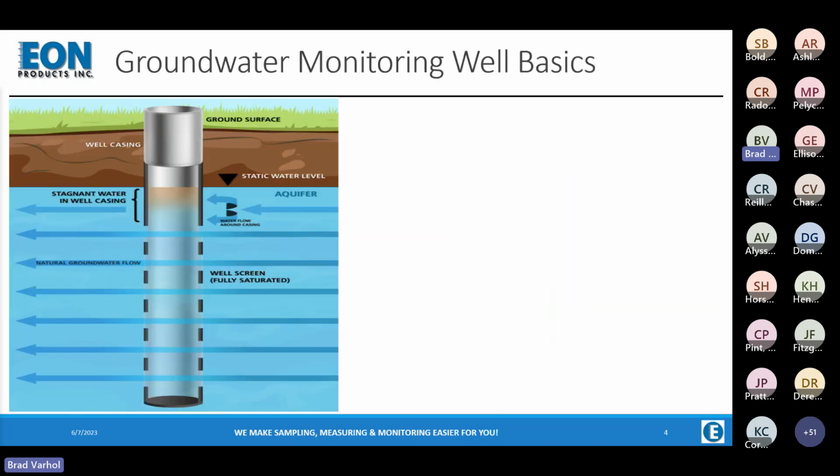And I will start by first apologizing to all of you who are very steeped in geology and groundwater conditions, but I'm going to start at a very basic level here by explaining what is a groundwater monitoring well. So if you look at the illustration here, we have the ground surface, and we have beneath that what in the drilling language is called the overburden or the dry sediments, and beneath that are the sediments that are saturated with water that is existing in these pore spaces between the sediment grains.